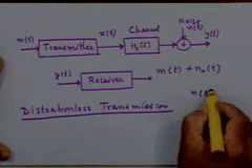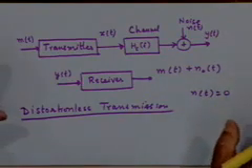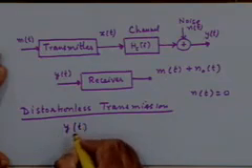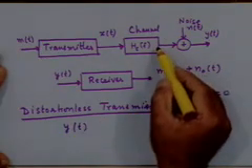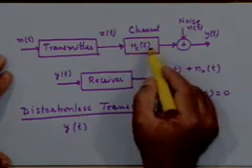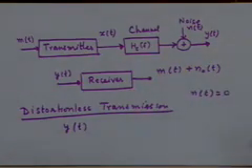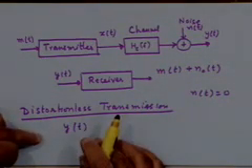So we'll assume n of t is equal to 0, because we want to concentrate on what kinds of distortions the channel can introduce, understand their nature, and see whether we can do something about them at the receiver, just to simplify the discussion. Now in this case your received signal y of t is basically the transmitted signal x of t convolved with the filter impulse response h c of t, the filter which models the channel.